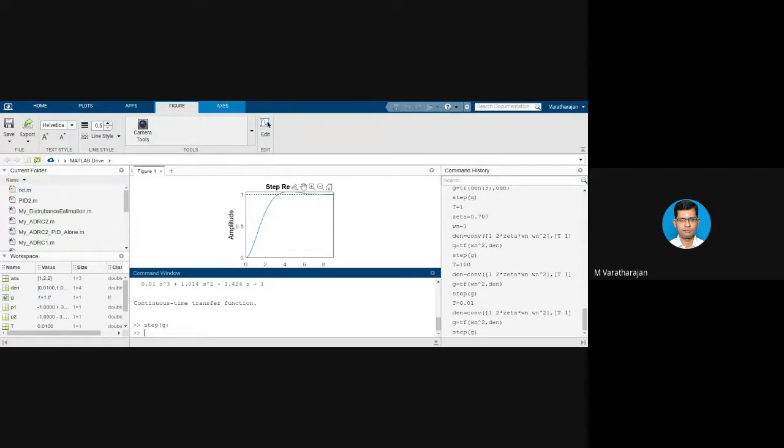Okay. So this is the effect of dominant pole, and this dominant pole helps to reduce the order of the system. While doing the next experiments, that is while discussing about compensators, we will see that the compensator effectively tries to adjust only the dominant pole of the system, okay, rather than the non-dominant poles. This is also a limitation as well, but all analyses are based on this limitation. In some sense, it is an advantage because we reduce the order of the system, but in many cases, it will also be a limitation.